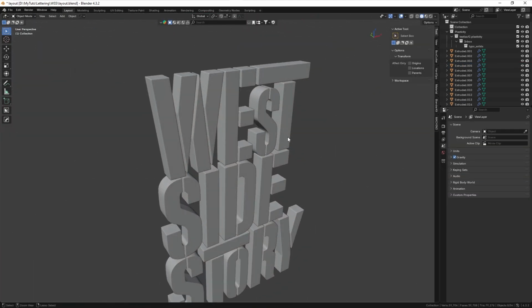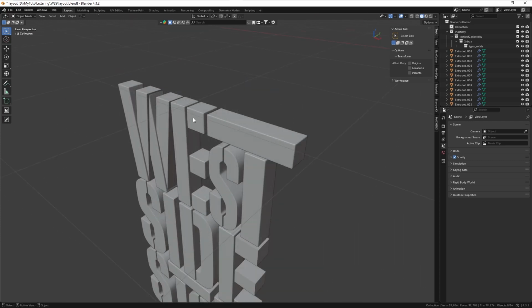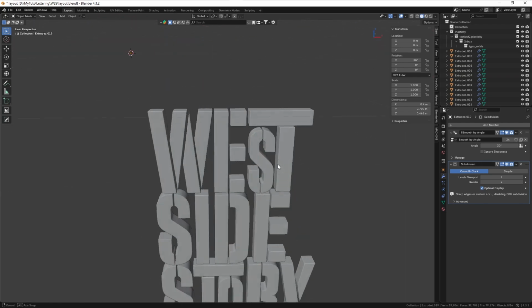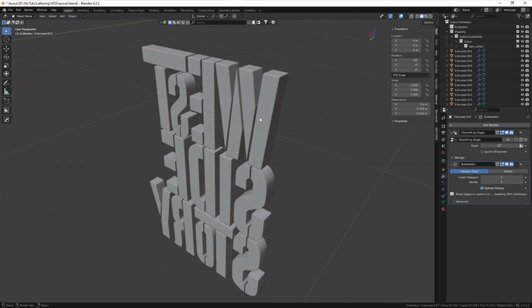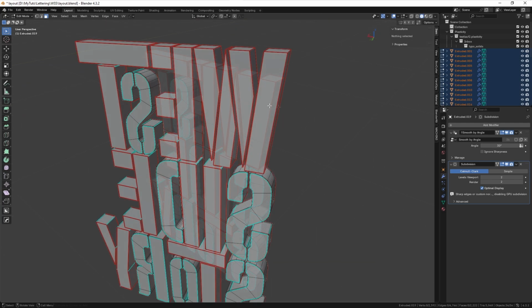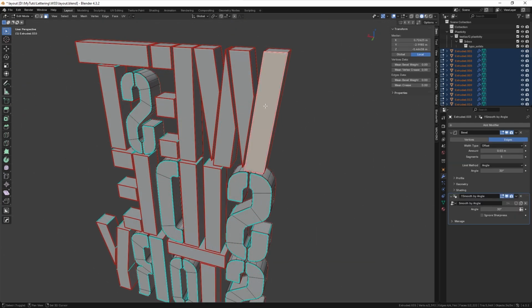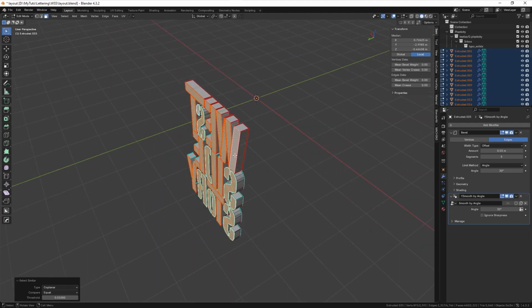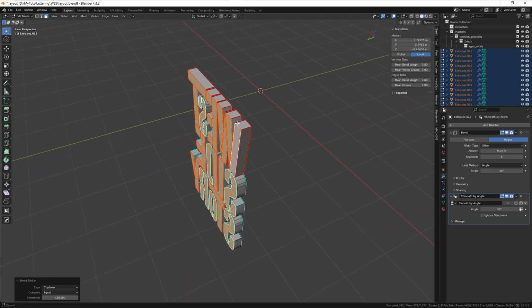Okay, that's what we have so far. A mixture of bevel modifier here and the SubDiv for the ones with the curvature. And that looks okay, that's what I wanted. And the next step is selecting all these guys. Go to face mode. Again, select one face. Shift G, C, coplanar for selecting all the faces in the same direction.